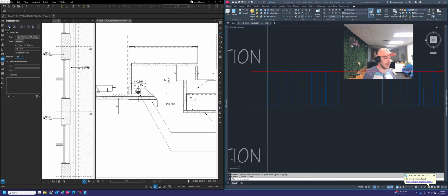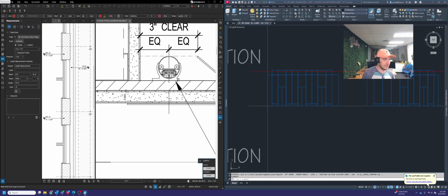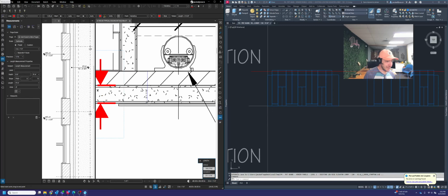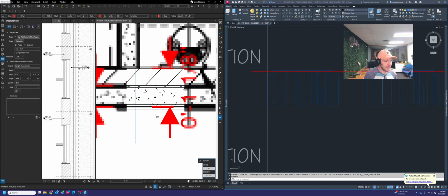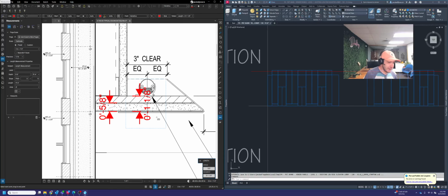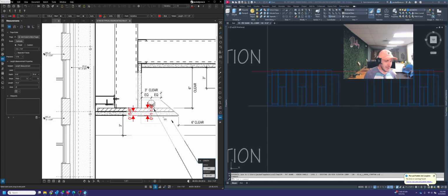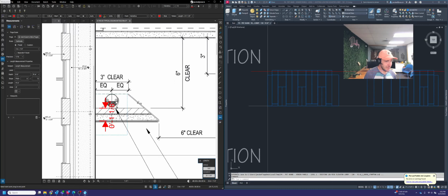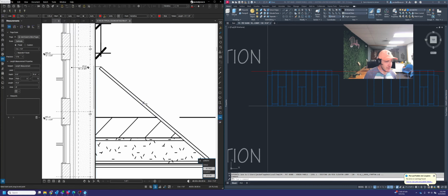And we're going to try to figure out a couple things. One, we know a couple of the dimensions that are already here. But two, I need to know, I'm guessing this is 5/8 because that's drywall. Drywall is usually measured at 5/8 thick. If I go from there down, that's an inch and an eighth, which I can deal with. That's not a big deal.